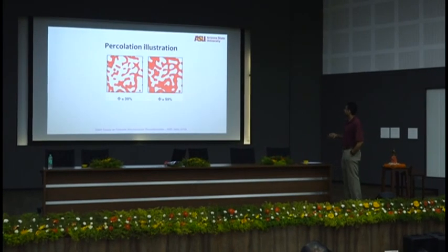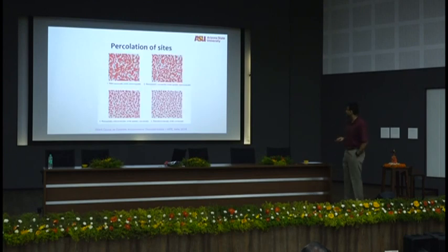Okay, so this is a 30% volume fraction. Can you see here? It's connected completely, right? I can go from here to here completely. See here? Right? When you get to 50%, most of my paths are blocked. I don't think I can go from this side to this side. See that? So 50% is roughly in 2D the percolation threshold.